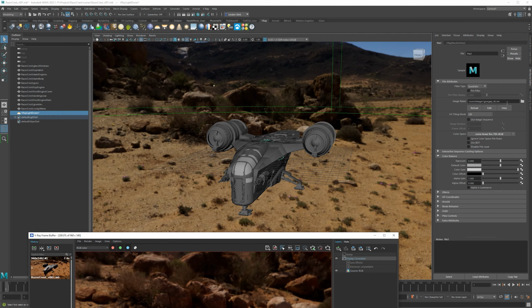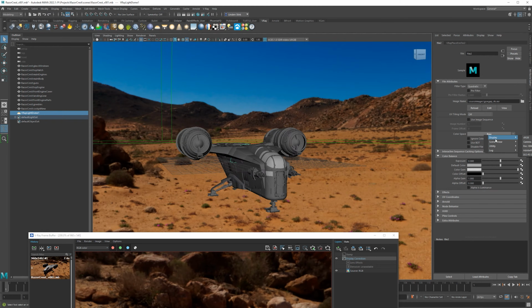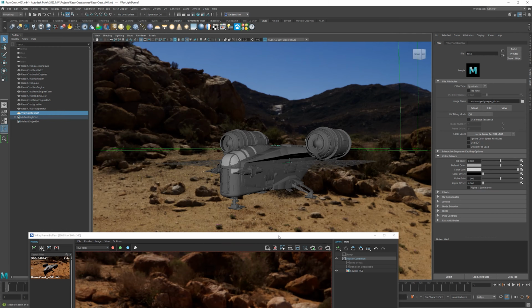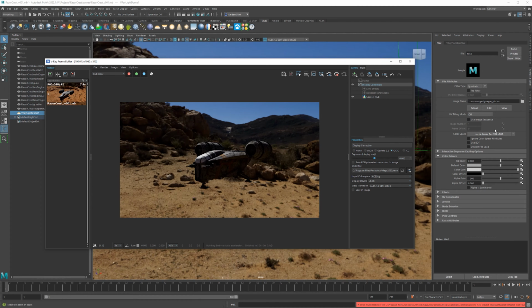And if we set that back to what Maya thought it was supposed to be, which is raw, it looks very reddish. That's because the color primaries are different with raw. So it's not doing any kind of correction, but we do want to say, hey, this is supposed to be in sRGB space. So we're going to set it there. That's going to give us a more accurate render from the original. If you did want a richer color, you should go about it in a different way. You should just color correct that image with sRGB. Now, there are circumstances where you might be using an HDR that is actually raw.